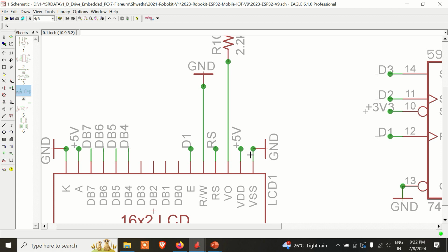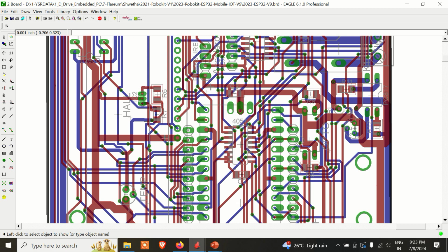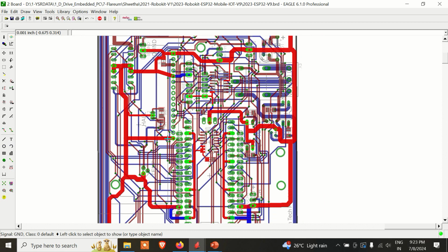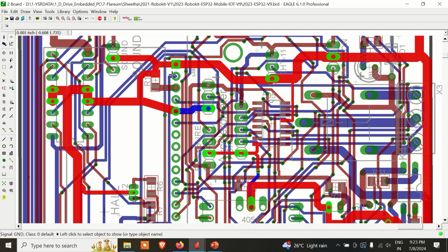If you have time, then wherever ground pins are mentioned, check the continuity, for example, along the entire track. If you see where the supply is, this thicker one is your ground. Now if I highlight this line, then wherever you see the highlighted red and blue on your entire PCB is called the ground line. Similarly, where is your VCC?